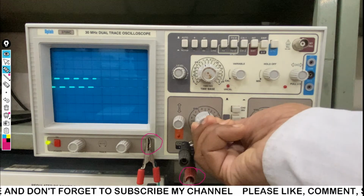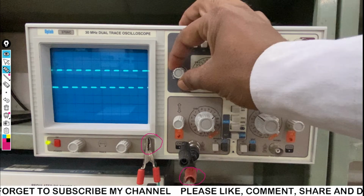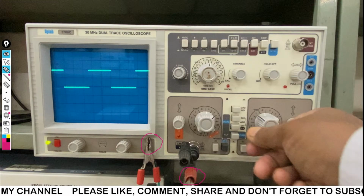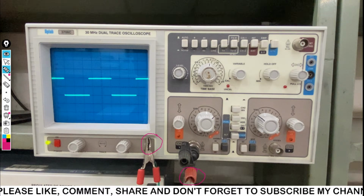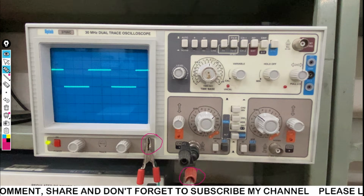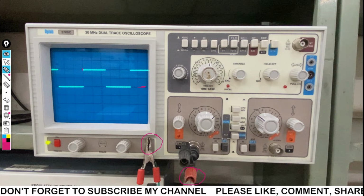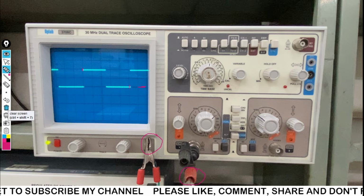You can look at here. Here I am varying the voltage per division knob, and there is a waveform that is called a square waveform. You can see here, this is the test waveform. By adjusting the time base knob, I can adjust the frequency, and by adjusting the voltage per division, I can adjust the amplitude. By the level button, I can place it on the x-axis, and by the variable button, I can place it so that we can start from this and end towards this for the amplitude and voltage measurement.